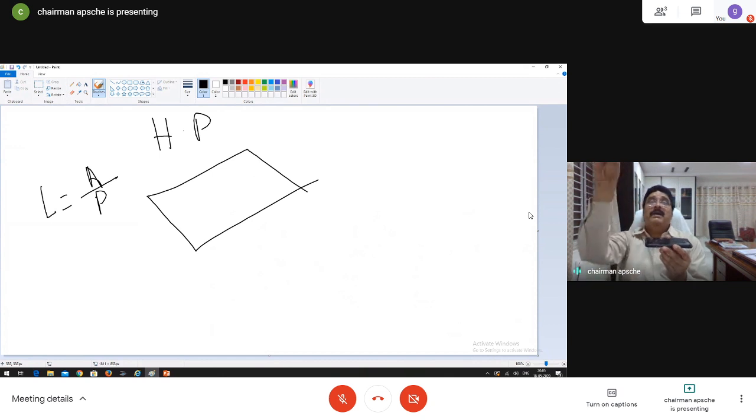When the plate is hot, a colder molecule at 30 degrees centigrade slowly drifted, came in contact with the 80 degrees centigrade plate, and it acquired the temperature of the plate because it is in physical contact with it. So now this is 80, its density is decreased, and buoyancy forces start. When it is moving up, it is creating a space, a vacancy, and immediately the next heavier molecule can come in and acquire heat.